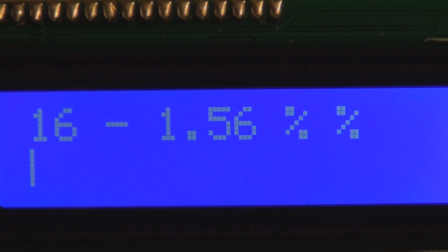So with the circuit that has the sketch with the progress bar directly related to the analog input, it gives us sort of a slow motion, step-by-step way of showing how the progression works. You can see the very first character, we're calling it a character, is the one single column of pixels all lit up. And we're not just turning on another row. What we're doing is replacing that character with a single row. We're going to replace it with the next character that has 2 rows lit up.